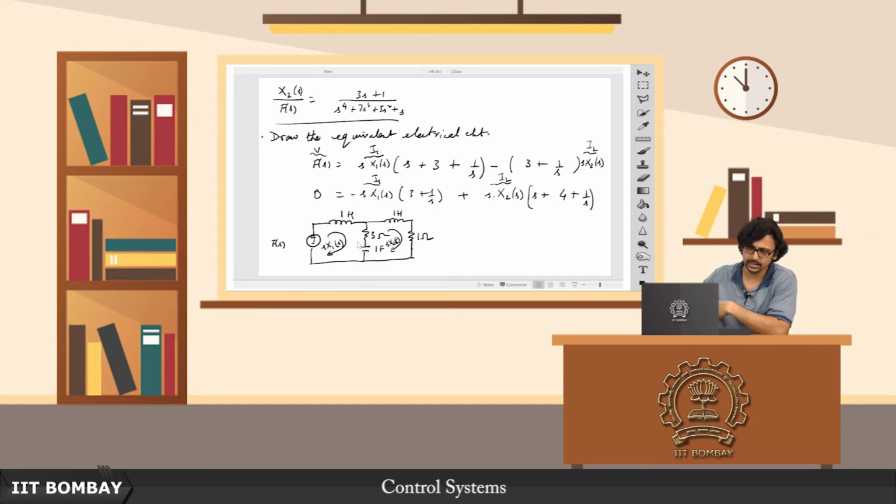On the other hand, if you look at the KCL, when you write the node equations, you essentially take that node voltage to be the unknown and you consider all the edges that are connected to the node. It's as if you ground together the other ends of the edges. So it's basically a parallel equivalent. All the currents flowing into the node or away from the node are like parallel paths all leading to that node. So I put it to you that the parallel equivalent is basically the KCL.